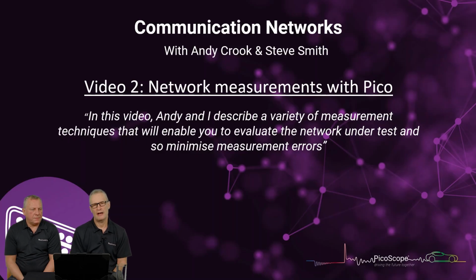The guided test will help and support, but even then, when you start making adjustments and what have you, you can get yourself lost. So little tip here: blame your measurement technique first if you think you've found something wrong, and prove and qualify your technique before you move on. This is a vital step: refining your measurement process is vital, and practicing on vehicles that don't have faults, yeah.